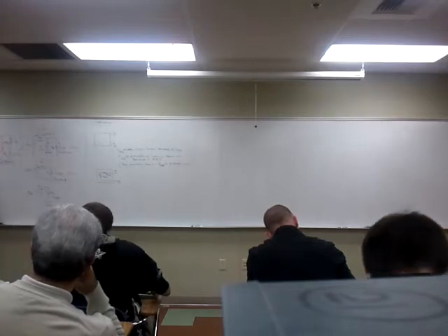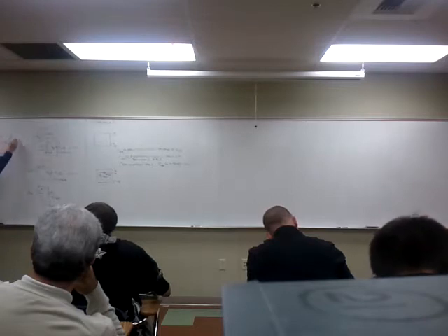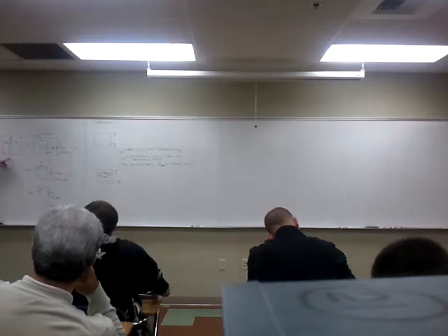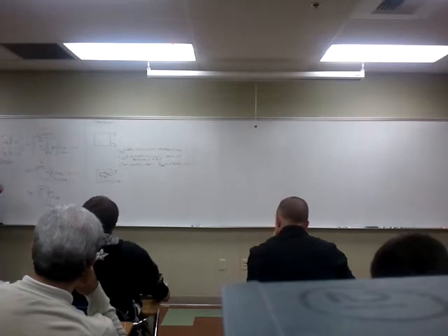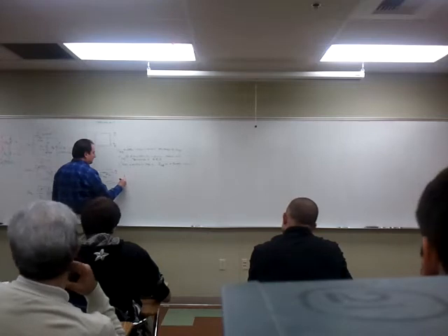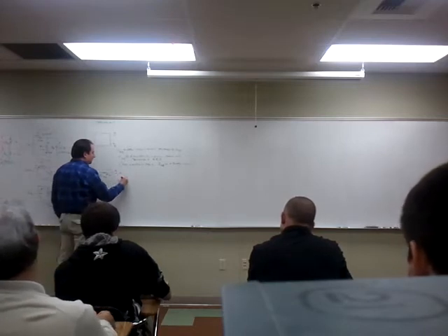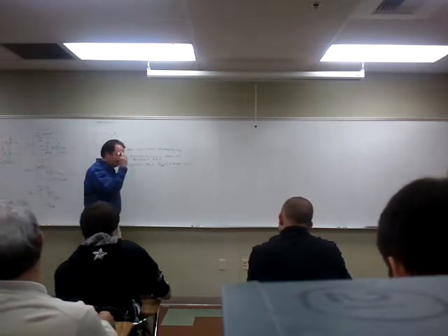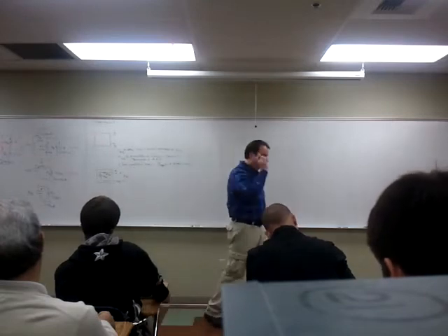In essence, you're going to take what's in this dotted line, in my example coming up. This is the box. And this resistor that I labeled RL is the resistor that I'm going to open or take out of the circuit to find the Thevenin equivalent.